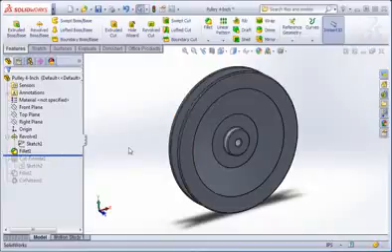We're going to use the rollback bar to create alternate designs of the model. We'll use the two-dimensional circular pattern on a new sketch, we'll extrude 3 holes, and then we'll add fillets to all the holes. Once we've done that, we'll change the number of holes from 3 to 4.